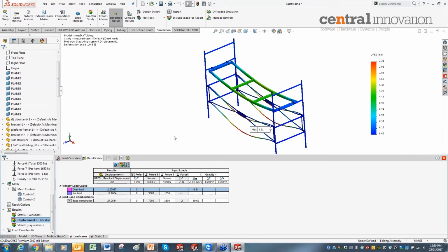I want to find that. Okay, now you can see after I activate the displacement plot, for the dead load condition, my maximum displacement is 2.21, and it is matching the sensor I created. I created a sensor for the maximum displacement. The sensor value shows 2.2, which is correct. And let me change it to a live load. I'll show you the displacement for the live load.